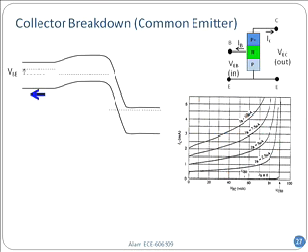The next thing is the common emitter configuration. In the common emitter configuration, the figure on the right shows the IV characteristics. It breaks down much more easily. Do you remember it has a lot of gain, right? IC over IB, beta, a lot of gain. But you see the problem with this, because it breaks down much more easily, and this is why.